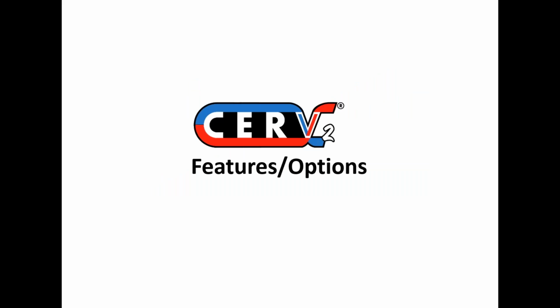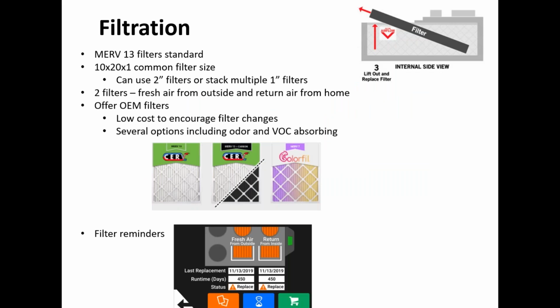We'll look here at the specific features and options of the system. Filtration is just a really important aspect of a smart ventilation system. MERV 13 filters are our standard filter rating for the CERV filters. They are common 10-inch by 20-inch by 1-inch filters, so you can find them almost anywhere. You can use a 2-inch depth filter as well, or stack multiple 1-inch filters to give you different filter characteristics.